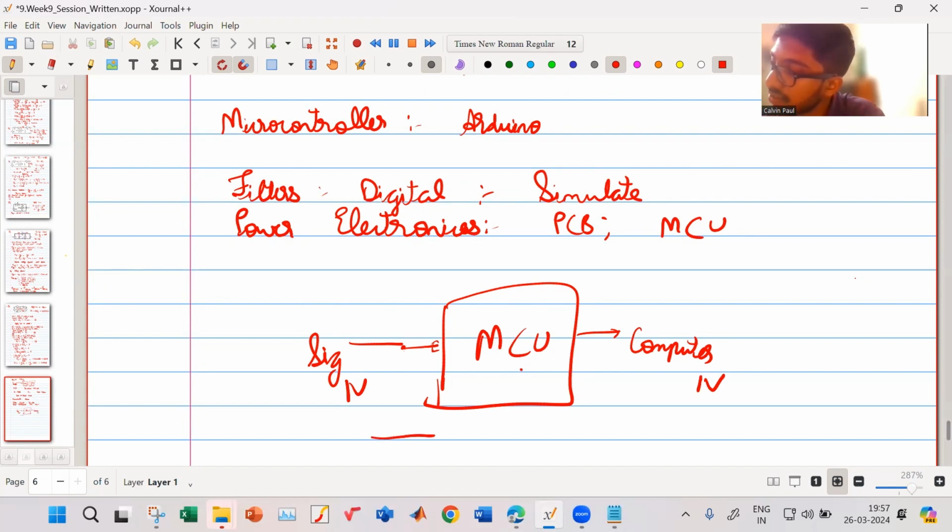Then once you do that, inside your MCU add one piece of code that if it is 1 volt, it will generate 2 volt here, so it should read some value 2. Then if that is working, you give some sine wave or something, and you see whether the computer is also showing this one.